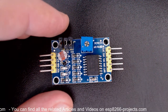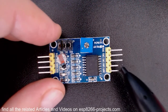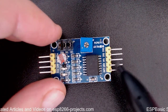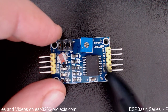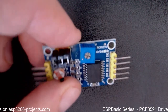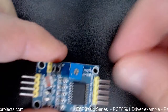For this example, I will use only the input 0, so the first input of the ADC, and to be able to use it, I will just remove the corresponding jumper. So basically I just need to remove this jumper from here.